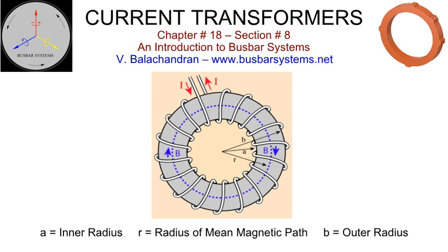The core cross-section area of current transformers located in main and delta connection will be small and those in tap-off connection will be large. It is a challenge to meet the specified instrument security factor for current transformer in the main bus. Many manufacturers recommend voltage-dependent resistance across the current transformer to meet the requirements. Similarly, it can be a challenge to meet the specified burden with the desired accuracy class for current transformer in tap-off bus. The magnetizing current for different mean magnetic paths with varying cross-sections will not be identical. This needs to be considered for differential relay inputs.